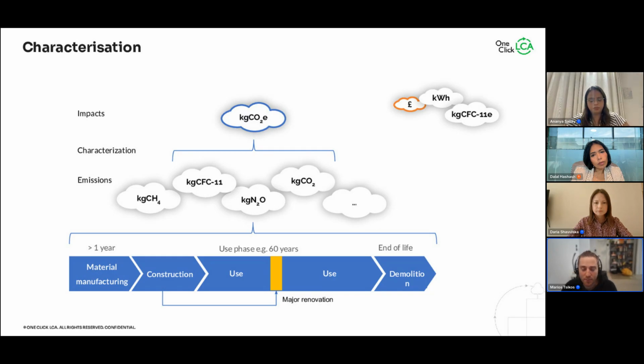Again, you're not going to apply this unless you're doing a product LCA, but when you're doing building LCAs, you don't need to worry. This is just background knowledge, really. So how does this work? We've got a factor that will convert a kilo of CO2 into, obviously, a kilo of CO2 equivalent. But for methane, for example, 1 kilo of methane is converted into some 30 kilos of CO2 equivalent. So we translate everything into kilos of CO2 equivalents because that's the most contributing greenhouse gas out there.